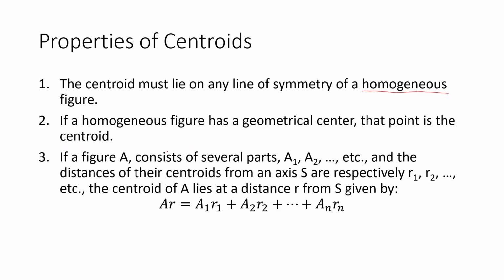And again, as discussed earlier, from the formula, bar x times the weight is equal to the summation of the different weight components, diba? Delta W. In our case, we're going to take several parts of the area. Let's say you're going to have an infinite number of areas, and then after that we're going to sum them up to get the distance of the centroid.